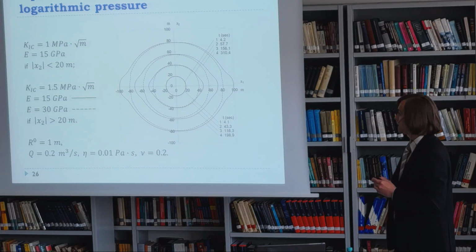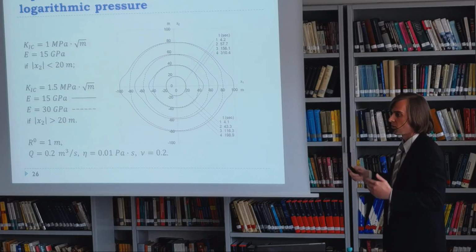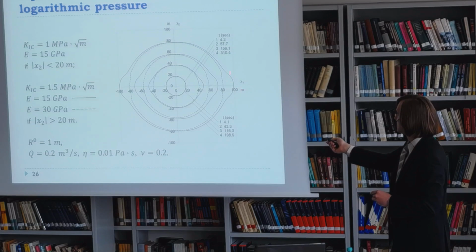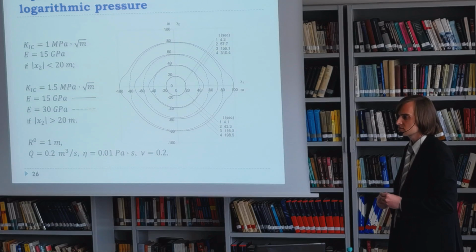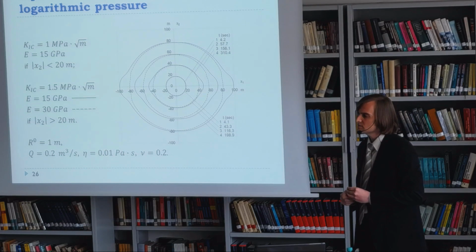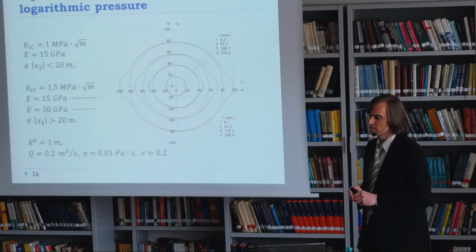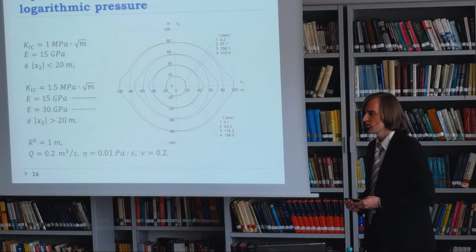As you may see from the time, it propagates much slower and less in the case of a high Young modulus. It's not an easy question. I think you may think in terms of G also, the elastic energy release rate, which is probably the right quantity, proportional to 1/E. It's a possibility. I'm not sure, but it could be checked. Yes, of course.